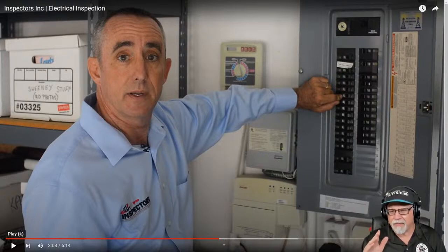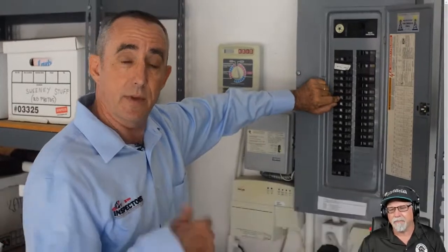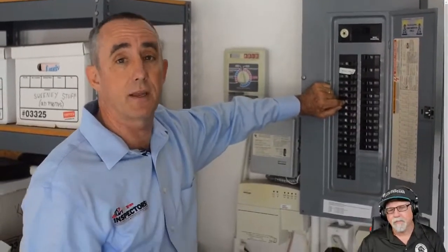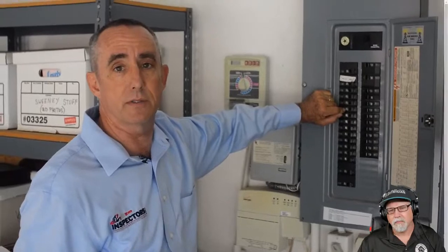And that looks like it's probably a Square D panel. Just remember, don't always go in there looking for the little sight glass to see it, because some manufacturers don't have that. Just something to think about. If they've tripped, the way you reset them is to turn it completely off and then turn it back on. However, if it trips again, you know you've got a problem, and you need to call a licensed electrician.